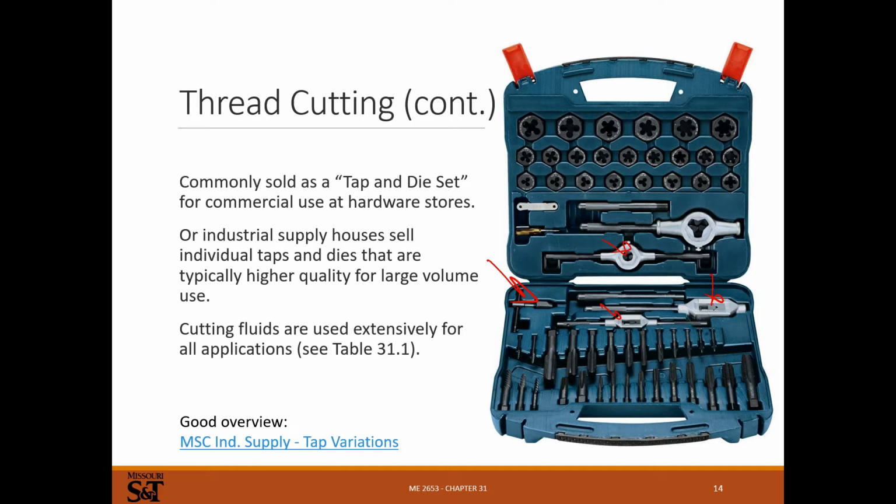When it comes to die handles, I've not run into a good die handle ever. With the ones like this, the set screw doesn't engage right, or something wears out and it stops holding on to the dies. Just not ever had good luck. You can start these things with sockets sometimes. Sometimes that works, and then you can use a socket wrench to drive these down after it's started. That works as long as you get deep well sockets, and a nice socket wrench is going to be better than one of these crummy handles. You're going to get what you pay for when it comes to taps and dies.